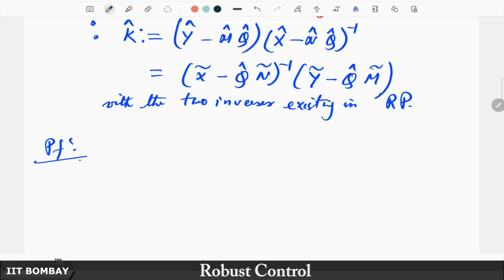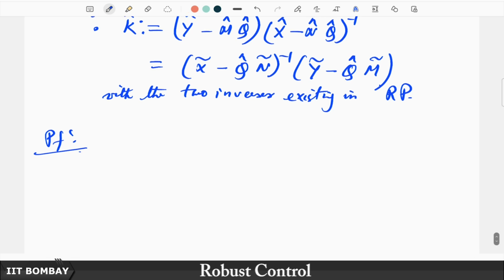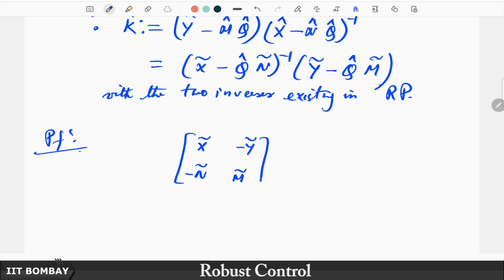Again, we will give you a sketch of the proof, not very great details, but it should be good enough to convince you. Consider that we already know this, which we proved in the previous lecture: when you have the left and right co-prime factorization of a plant, given by the tilde, the left co-prime, and the hat, the right co-prime factorization, n hat x hat, that we have used in our convention. I am going to leave a little bit of space here and you are going to immediately see why. So, this is true.